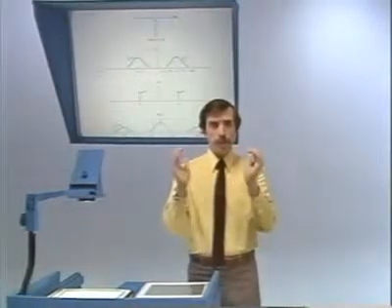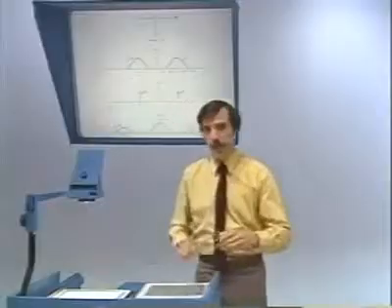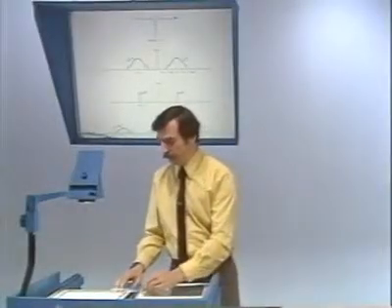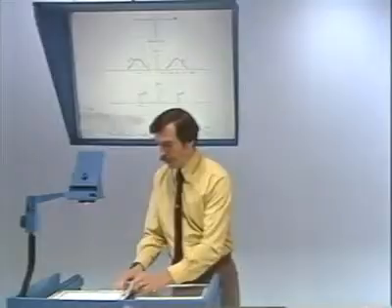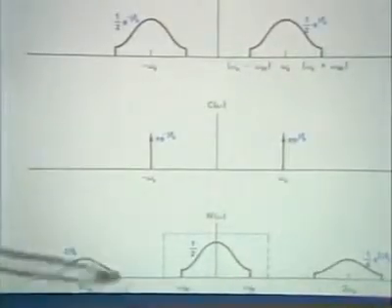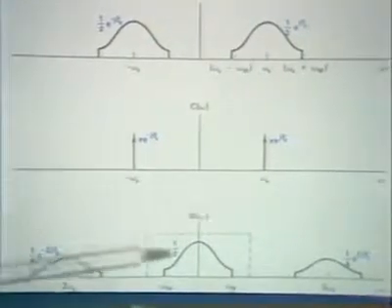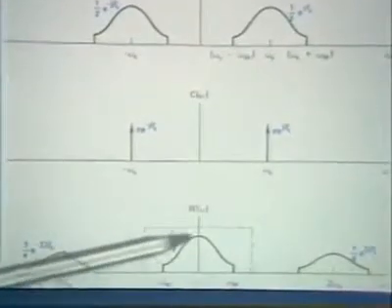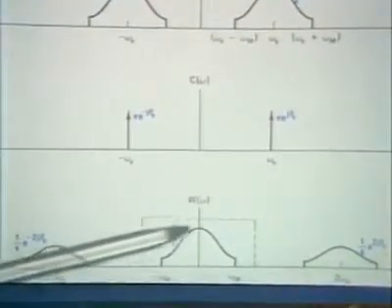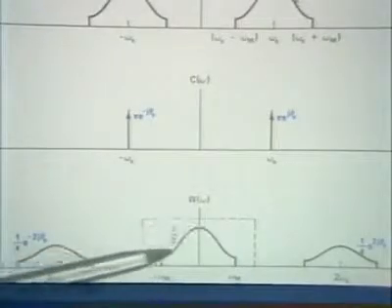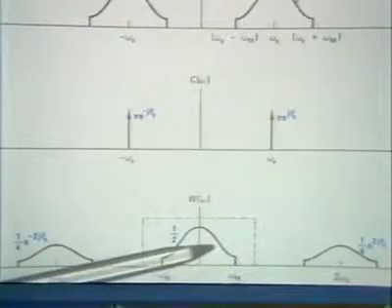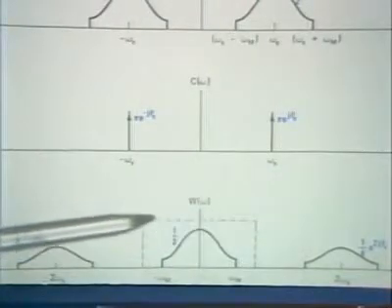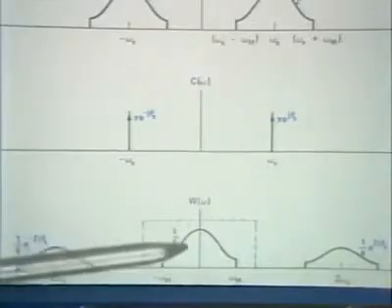So in fact what we would do is put the result of this through a low-pass filter. The low-pass filter would retain the part of the spectrum around DC and eliminate the remaining part of the spectrum. So we would keep this part and eliminate the part of the spectrum that we have over here. And let me just draw your attention to the fact that because of the way the algebra works out, the amplitude of this replication of the spectrum is half what the original spectrum was, and that means that ideally to keep scale factors correct, we would choose the amplitude of this to be 2 to scale this back up to 1.